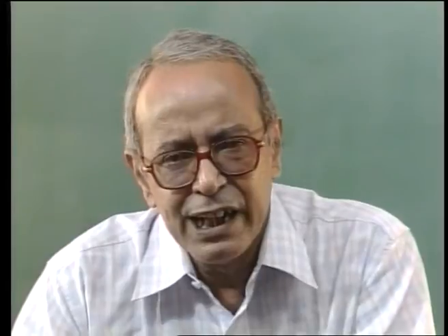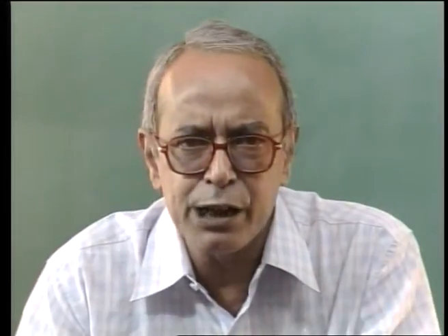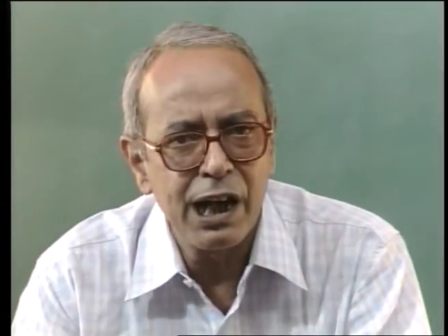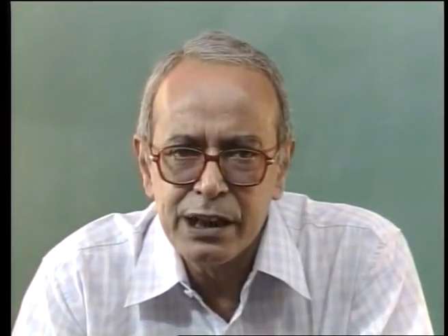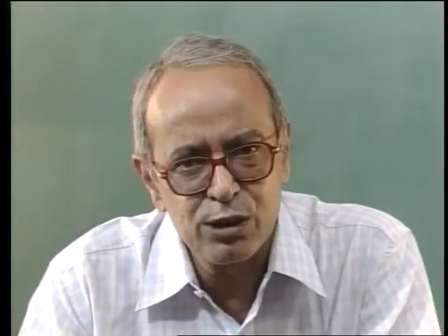At this stage, let us recall that a free, that is an unconnected rigid body which does not have any kinematic pair with some other rigid body, a completely free unconnected rigid body has 6 degrees of freedom in a 3-dimensional space. 3 of these degrees of freedom are translational, say along 3 mutually perpendicular directions x, y, z.